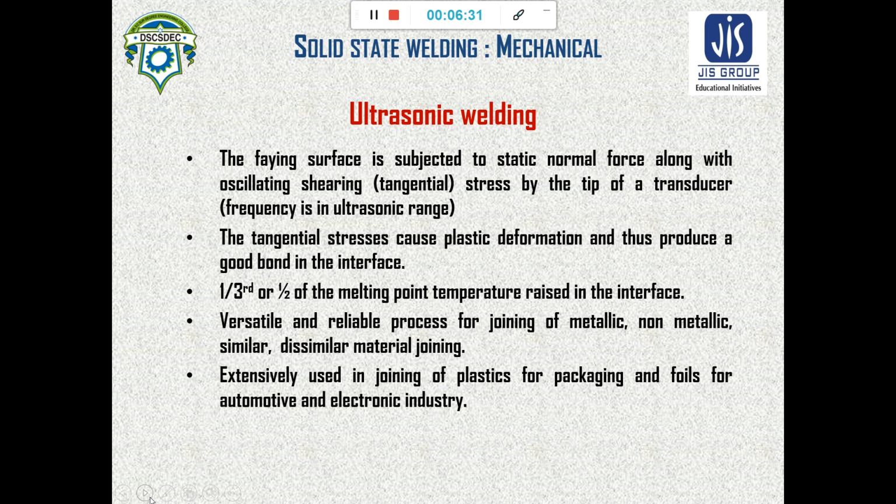That tip of the transducer is known as horn, and the frequency of that oscillating vibration is in the ultrasonic range. What will occur? Due to this axial and tangential stress, friction will be generated in the faying surface. So plastic deformation may occur.